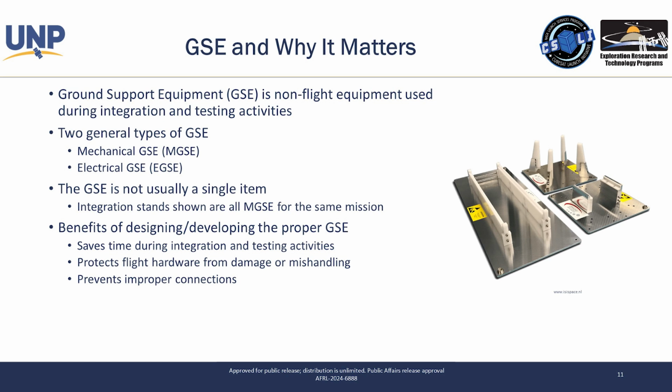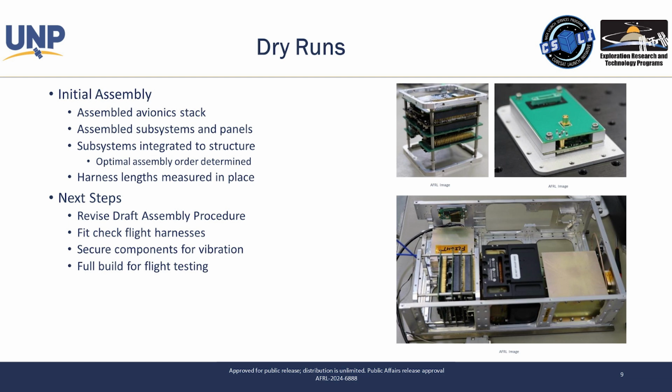Similar to the assembly procedures, you're designing the system and how it's going to go together and how it's oriented. A good example is a base plate sitting on the table, and we bolt everything either down to that base plate or to one of the sides. So you can build everything on the plate and then fold the walls up around it, which was very convenient. In this case, we don't even really need ground support equipment as typically used. We're using a table, which technically counts.